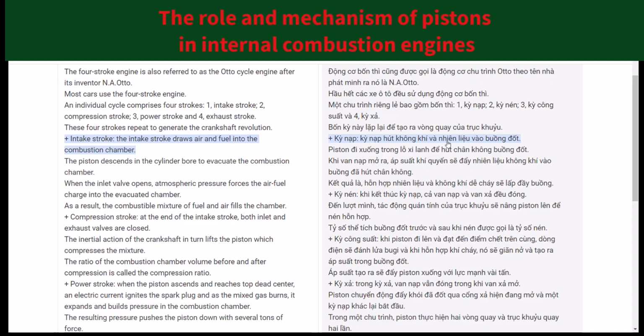Intake stroke. The intake stroke draws air and fuel into the combustion chamber. The piston descends in the cylinder bore to evacuate the combustion chamber. When the inlet valve opens, atmospheric pressure forces the air-fuel charge into the evacuated chamber. As a result, the combustible mixture of fuel and air fills the chamber.